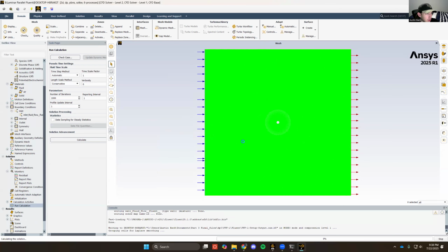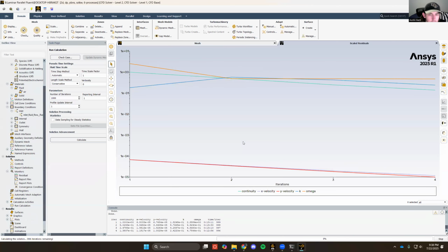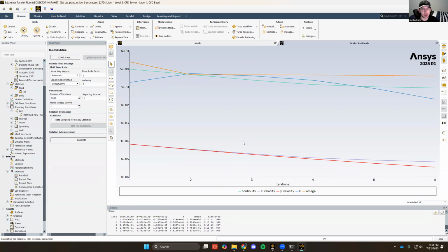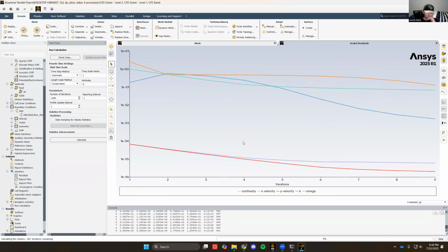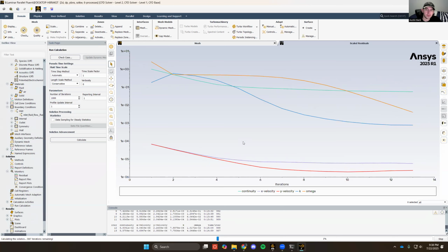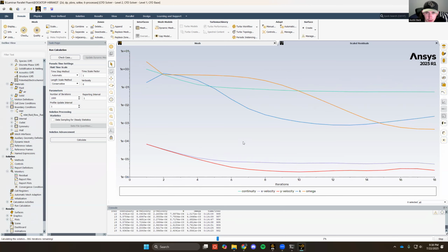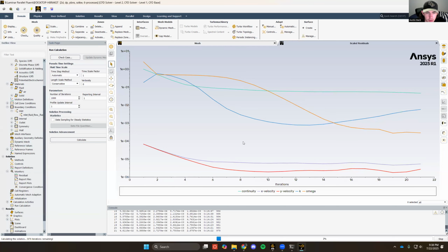And in this case, this is the laminar. So this should be the biggest wake region. Our CD should be the highest. So we're going to let this run. Yeah, you'll see with this one, these iterations take a lot longer, which is why that simple was so nice. But we're just going to let this run and take its time to get down to 10 to the negative 3.